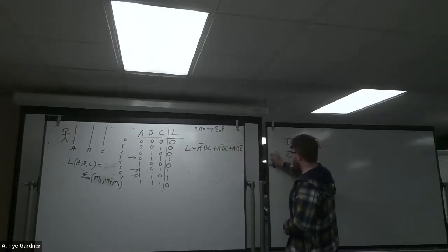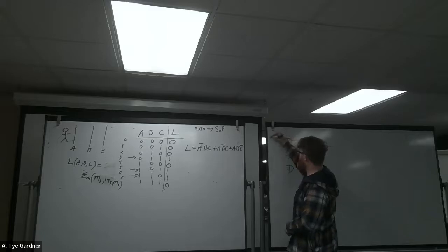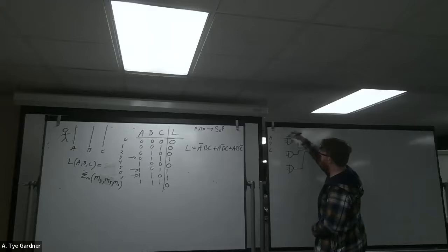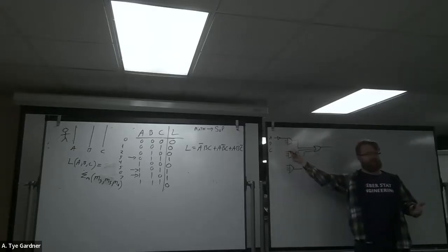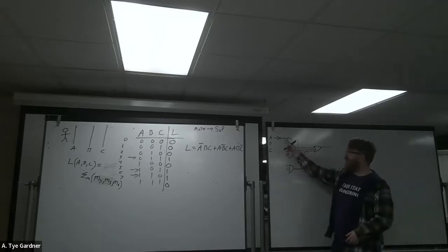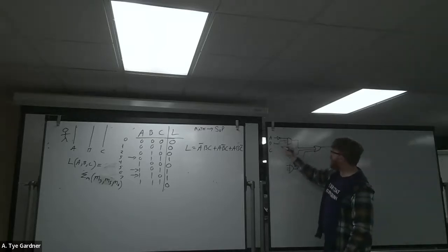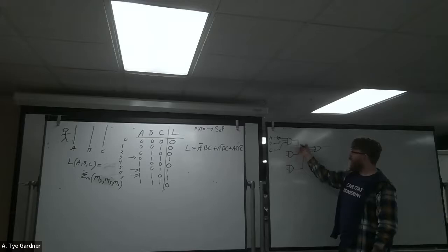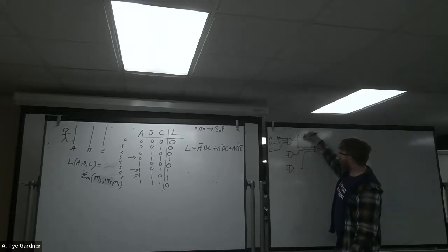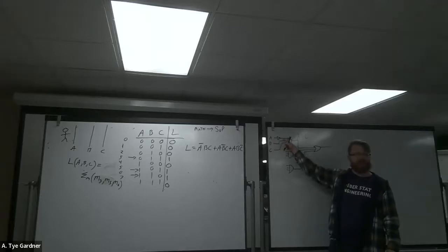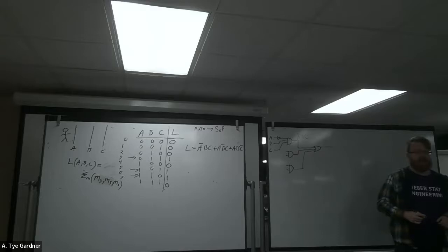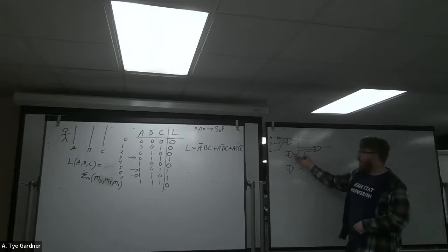So sometimes how you'll see this drawn will be something like this, is I'm going to have an A, a B, and a C. And this first one, I need to make not A, right? I've just inverted it. If this is A, that's not A. And now I have a gate that says if not A and B and C, right? Because if I have a 0 on A, that makes a 1 on this side. And then I get 1, 1, 1. It makes not A and B and C.